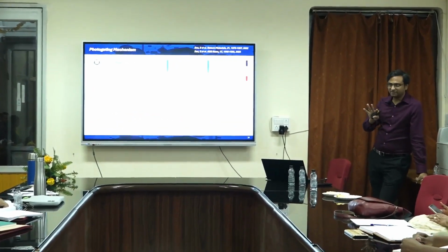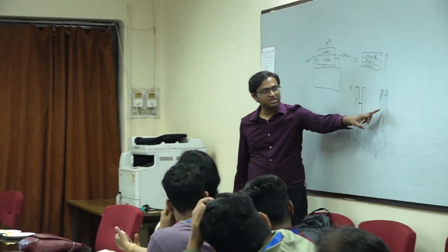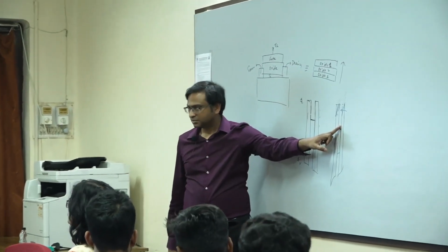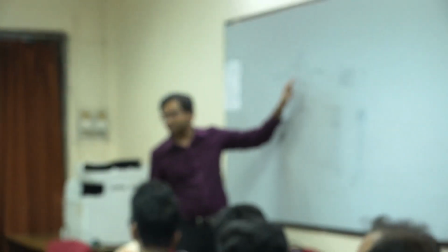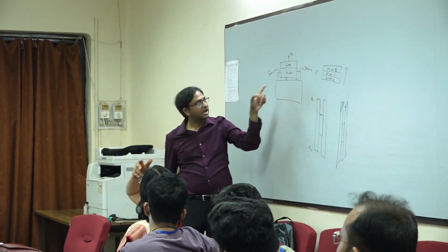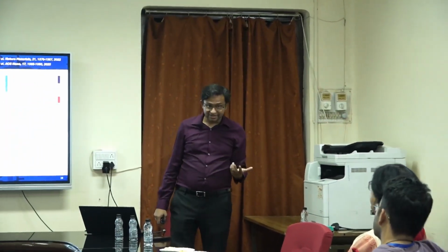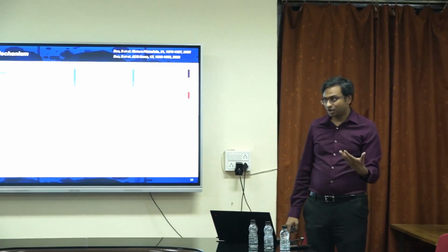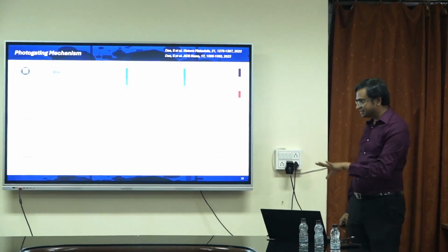So we learned about memory devices, right? What we learned about memory devices is that by applying voltage, you are storing charge here, right? Correct? Now think about, instead of voltage, I could do it with light, because with the voltage I was enabling this carrier to tunnel from here to there, right? If I was able to generate carriers by shining light, I could also trap charges over here. Make sense? Right? So then I get something called the photo gating effect, because it is photo memory. It's almost like what we see, we remember. Right? So it is exactly the same principle.